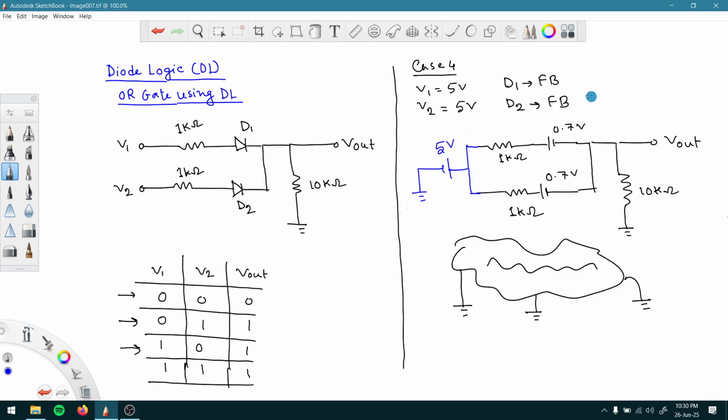So for our case here, we are not considering anything about the capacity of the voltage source. We are just trying to analyze the circuit, how much voltage we are getting at the output. That's why if we have two different voltage sources in parallel to each other, which are equal to each other, like we had here 5 volt, that means we can just replace those using just one voltage source of 5 volt. The similar concept can be used here also.